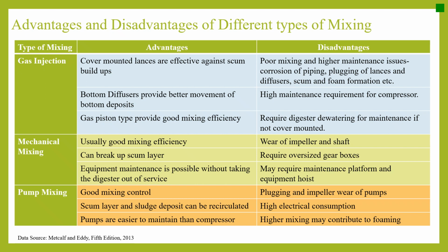Pump mixing advantages: good mixing control. Scum layer and sludge deposits can be recirculated. Pumps are easier to maintain than compressors. Disadvantages: plugging and impeller wear of pumps, high electrical consumption, and higher mixing may contribute to foaming.